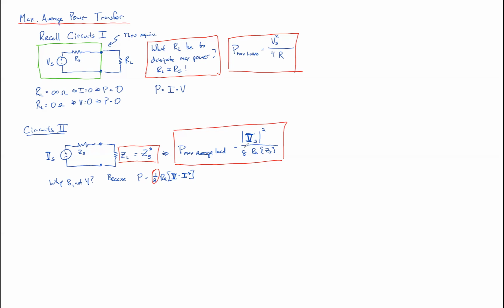Okay, just a quick thing, realize that here we're still measuring voltage in actual units of volts and not VRMS. If we did it in VRMS, instead of this being an 8, it would be a 4. Let me give an example.